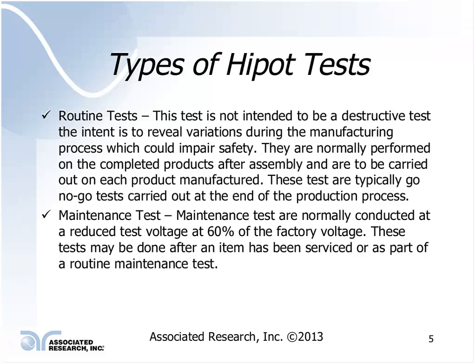That's very common. Okay. But these tests are normally done at the end of the production line, and again, their intent is to reveal any potential safety problems that could have happened, such as cut insulation or component spacing that might be too close.